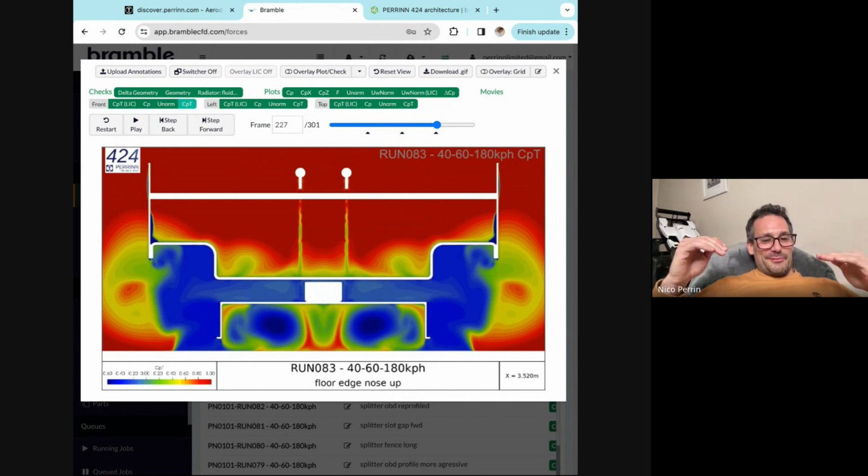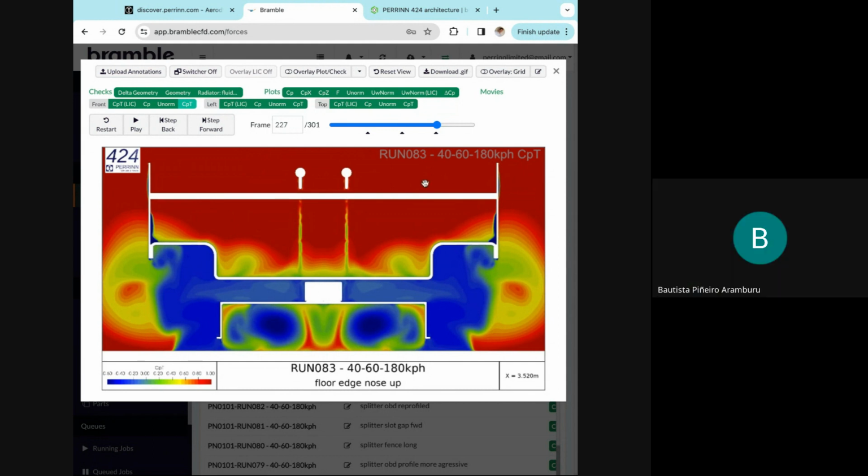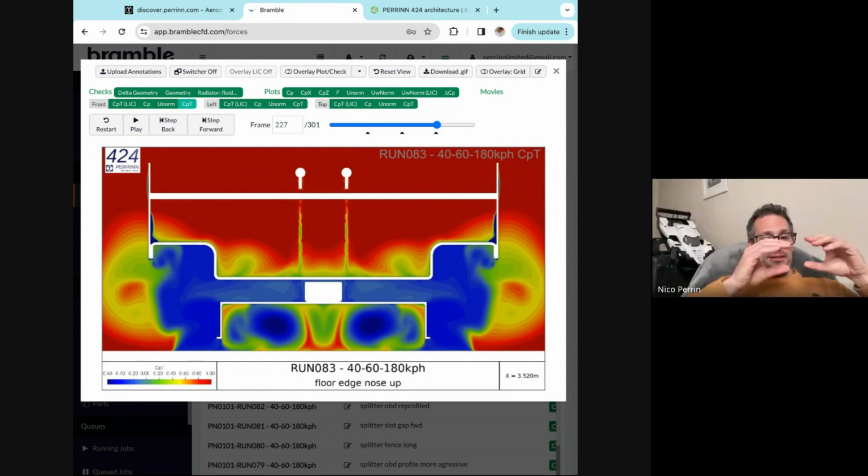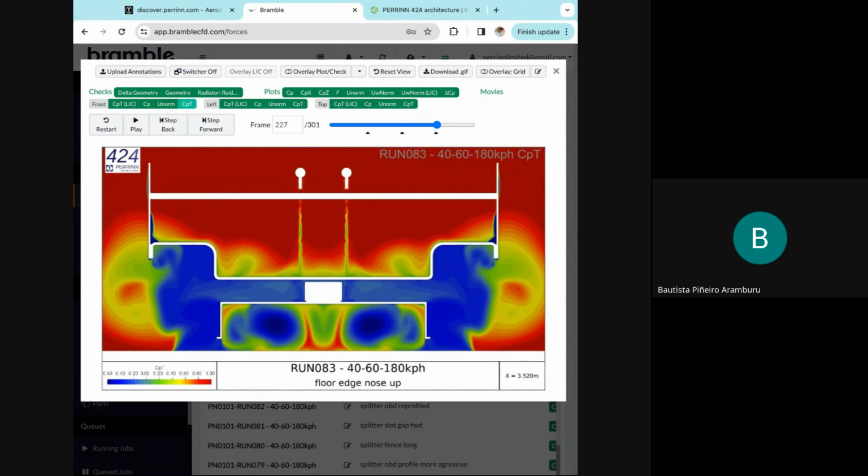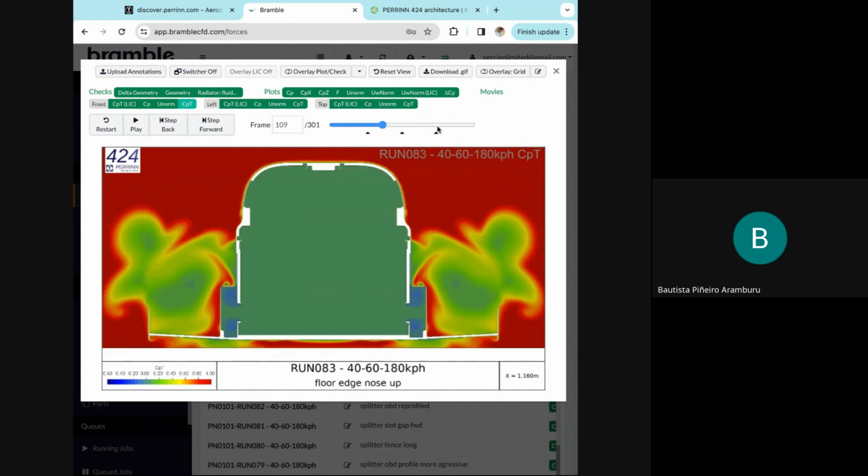And I have people sometimes saying, why don't we go low and at the back like the old Group C cars? But they didn't have CFD and as much testing time at the time. But what you find is the rear wing wants to be high just to work in this very high quality, high energy flow. And then it's like you put the wing in the best environment possible for it to work at its best.